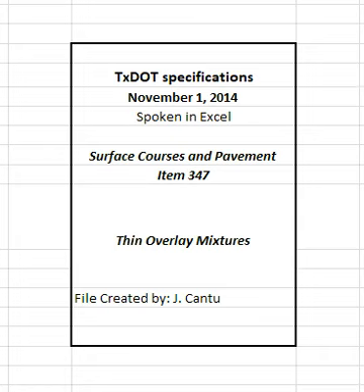Provide the engineer with the thermal profile of every sublot within 1 working day of the completion of each lot. Report the results of each thermal profile in accordance with Section 347.4.2, Reporting and Responsibilities. The engineer will use a handheld thermal camera to obtain a thermal profile at least once per project. Suspend operations and take immediate corrective action to eliminate severe thermal segregation unless otherwise directed. Resume operations when the engineer determines that subsequent production will meet the requirements of this section.